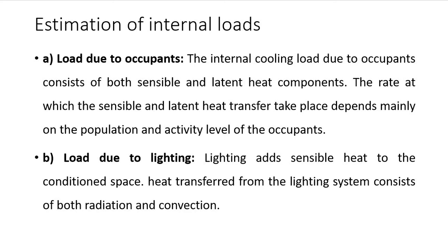From where does the latent heat component arise? When we are exhaling, that air will contain some moisture content, as well as when we are sweating, that sweat will evaporate and that will add moisture in the air. So the heat energy radiated by our body will cause sensible load, and the amount of moisture coming out from our body will cause latent load.